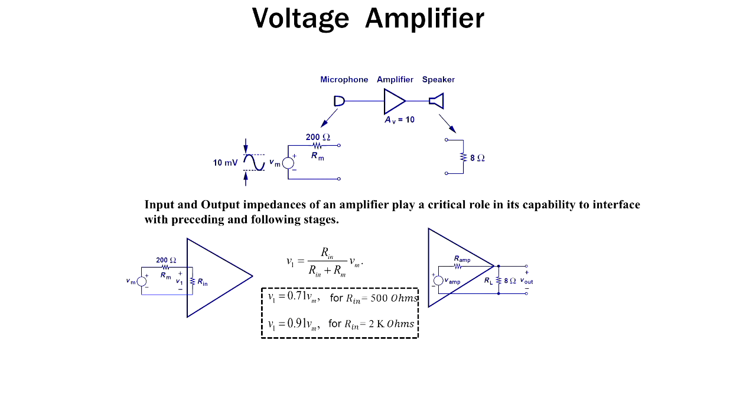Why? Because you have a coil inside the speaker, because the speaker is operating just opposite of a microphone. You are giving the signal and then the diaphragm is vibrating. You are driving it using the signal, then the diaphragm vibrates and you hear the sound. The coil is there, the magnet is there, and when the current goes through the coil, that is when the vibration happens. Because of that, the input impedance of the speaker is very small, maybe 8 ohms, sometimes 10 ohms, sometimes 6 ohms.